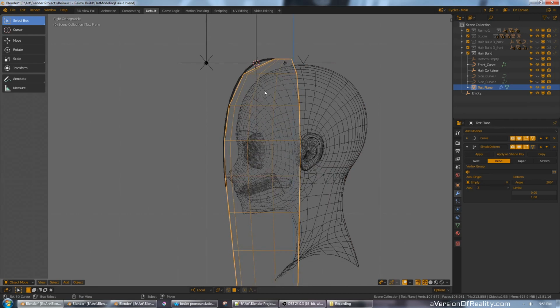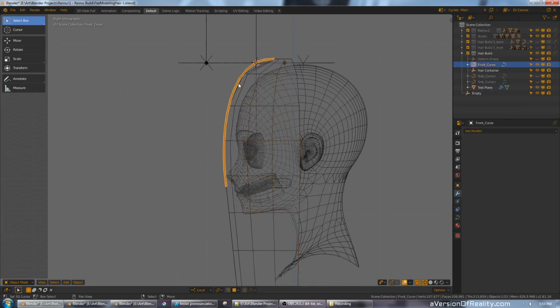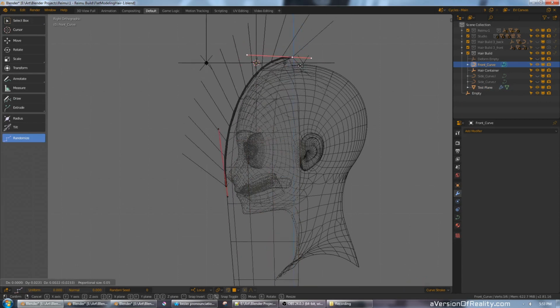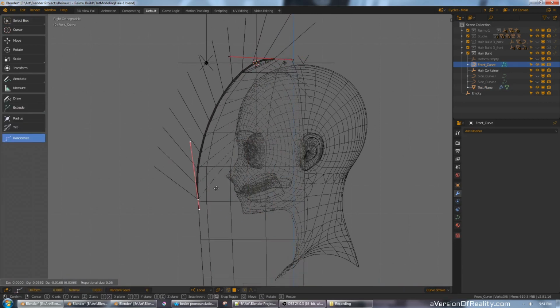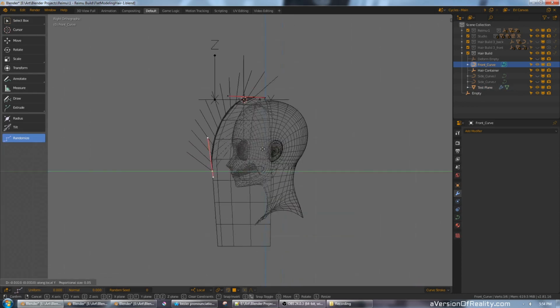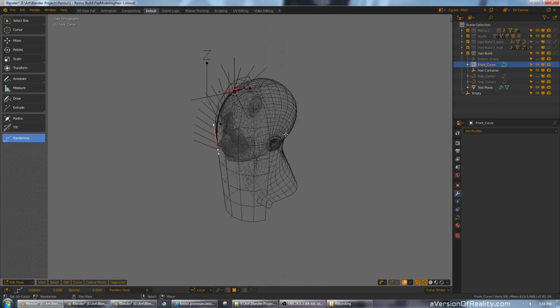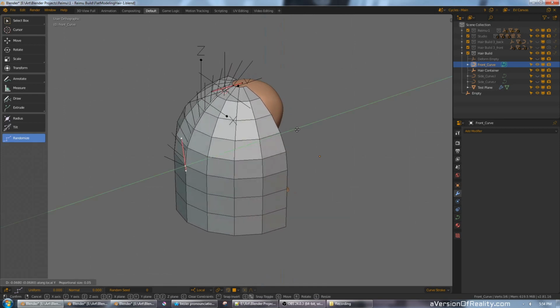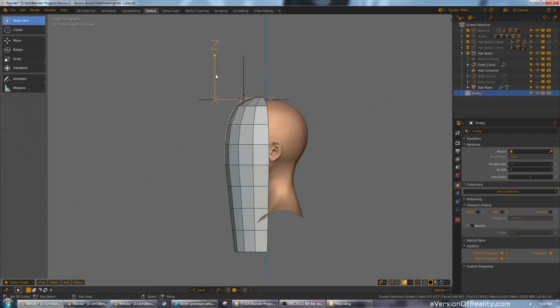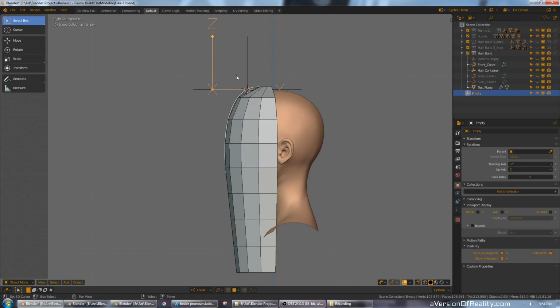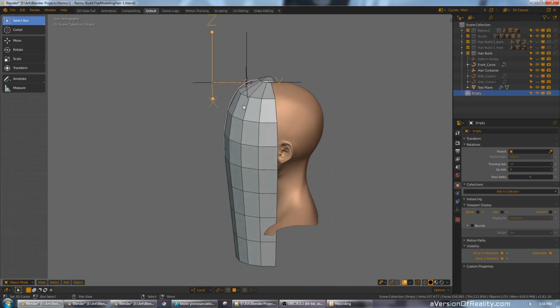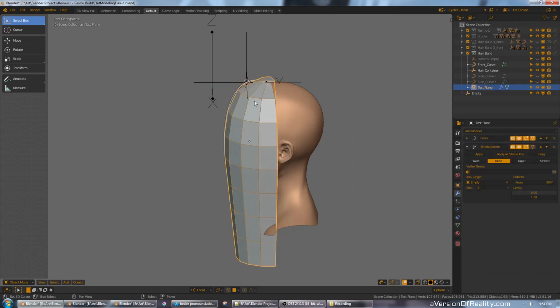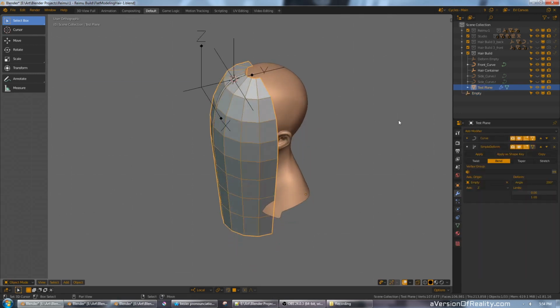But now we can see that the front profile is being defined by our curve, and of course edit. And the rest is being defined by the simple deform. Now it's worth observing, as I move these points, it is going to change the shape because the curve modifier is acting before the simple deform. And the simple deform is bending the whole mesh around this pivot point. So if the mesh changes size, then the shape of the bend is going to change as well.